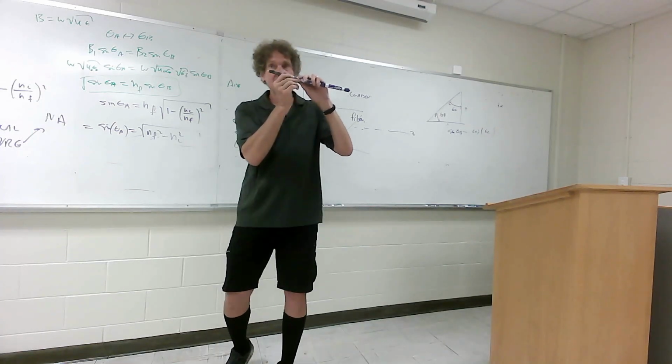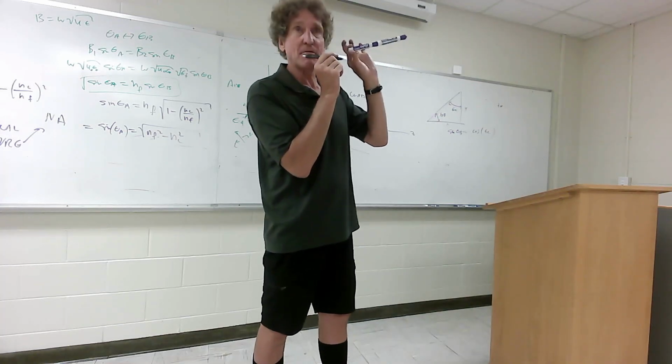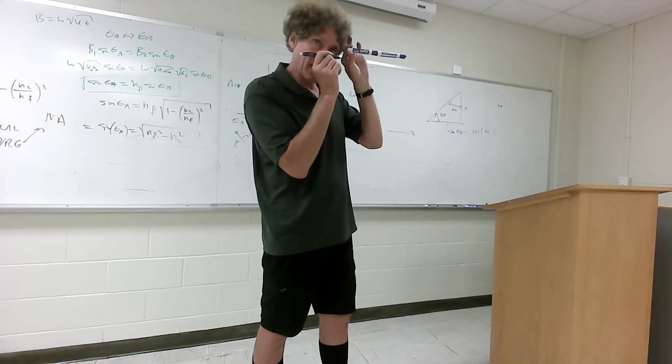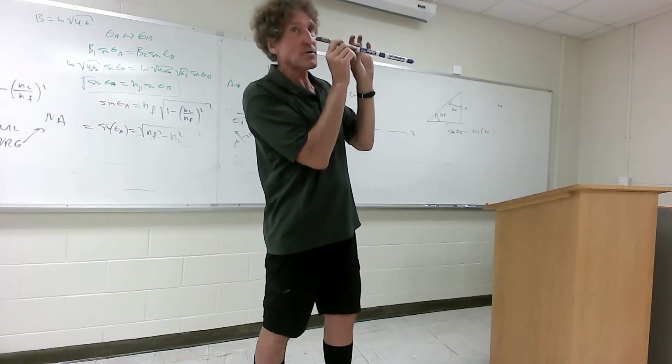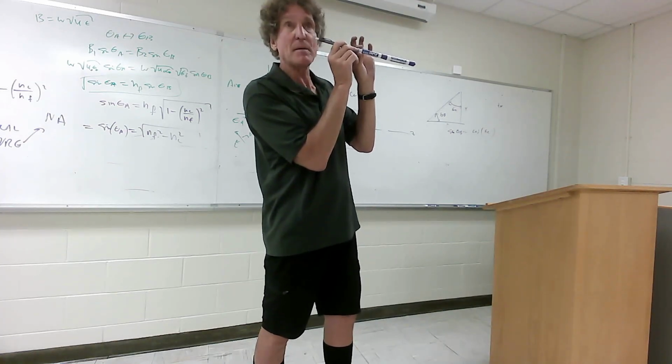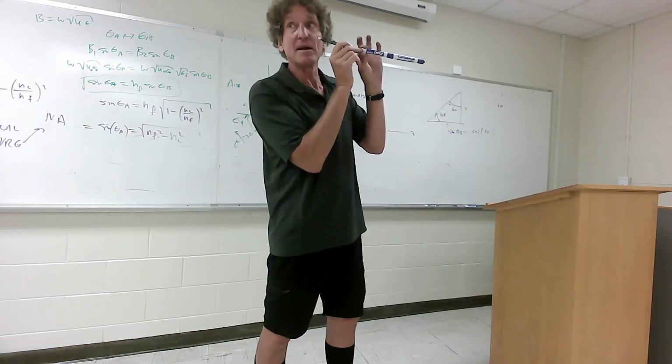Now when you align these things, you have to understand, fiber is super thin. 5 microns, 10 microns thick, all right? You got another piece over here. You're going to have to align that thing to the order of microns of accuracy. And remember this much, when you have a laser and coherent light, it comes out at just one angle, basically.